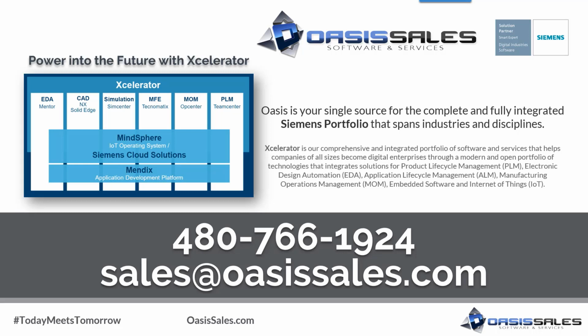One of the last questions we have is, what PCB interchange formats does Flotherm support? We saw on the screen a little bit earlier, there is CCE, which is from Expedition. That's a Mentor Graphics PCB tool. The most common by far is ODB++. That's kind of like a STEP file for PCBs. Almost all tools can export that.